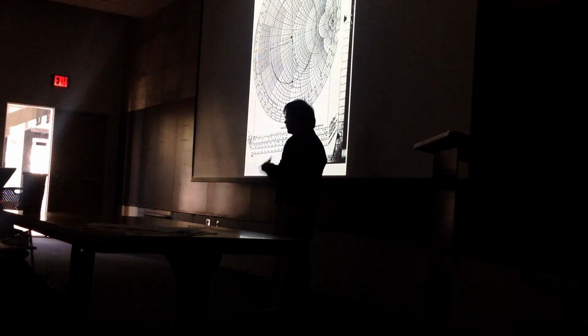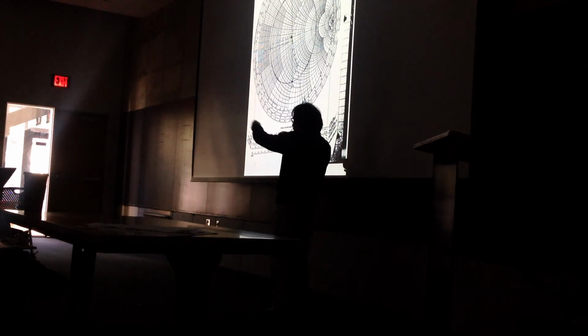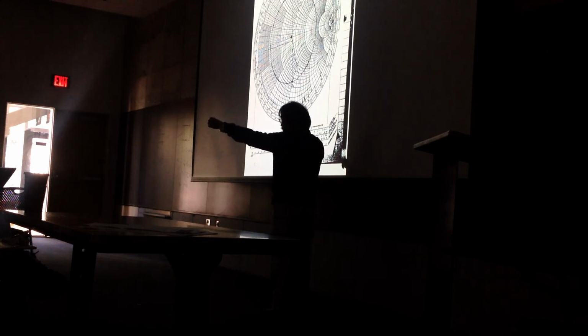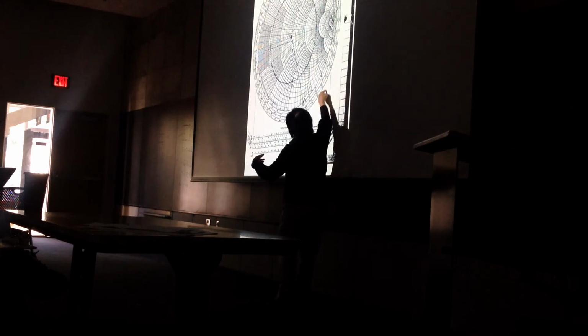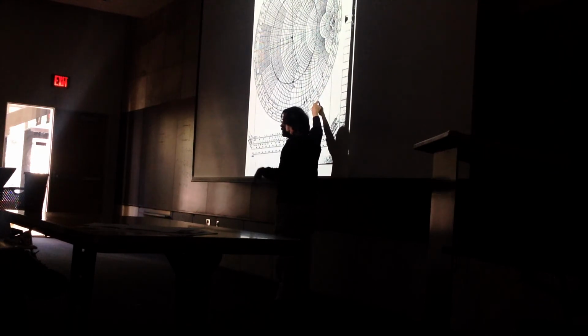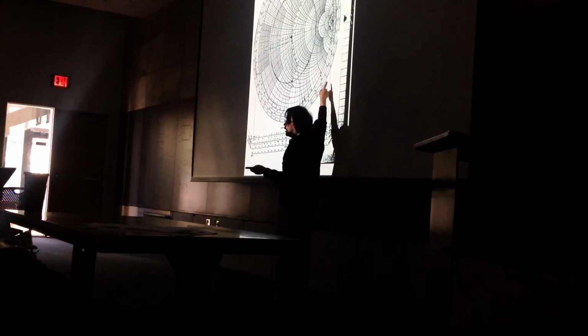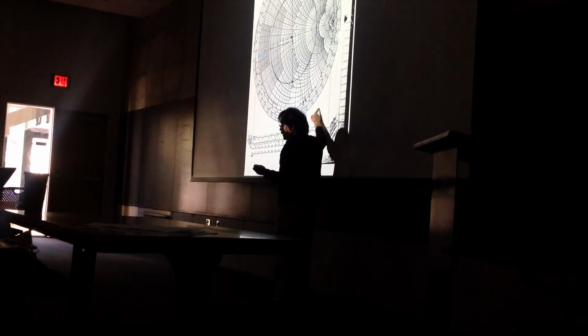So let me repeat one more time. This is where the transmission line is kind of like a magic in a way. You can take a short circuit, a wire which is a short circuit, and by adjusting the length of your transmission line, it will become an inductor. You go from that short circuit and you travel down here. Every single point down here is an inductor, because this is admittance we're talking about. So you see, you can take a short circuit and make it an inductor.